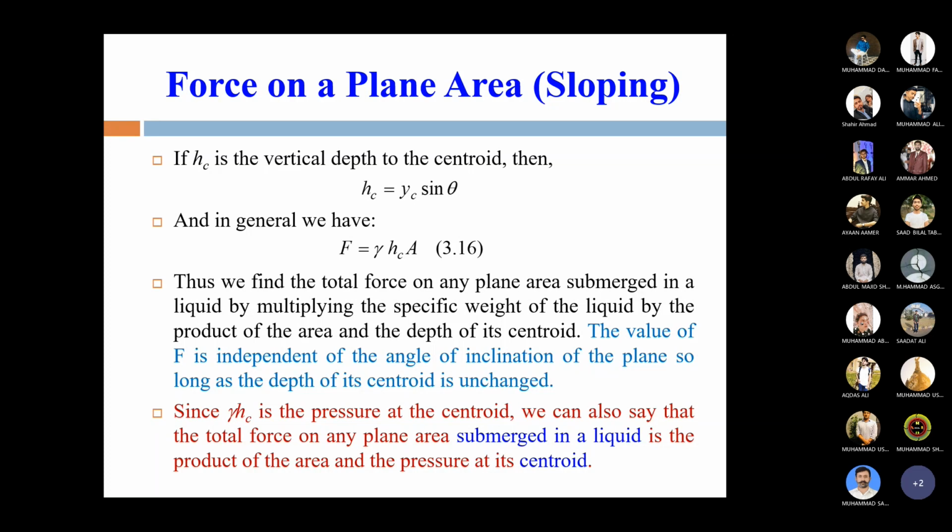So do you know how we can calculate the force? This is the formula for force, which is F is equal to gamma h_c A. And what is h_c here? Vertical depth of the centroid. Vertical depth of centroid. Very good. Of body or of water surface?